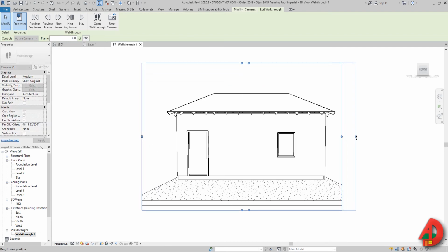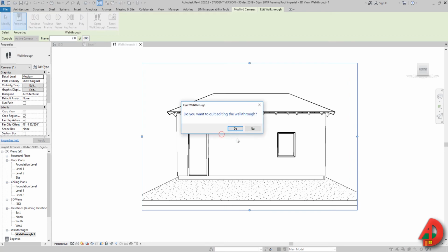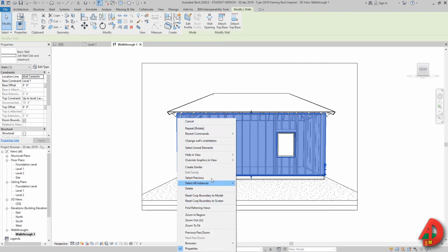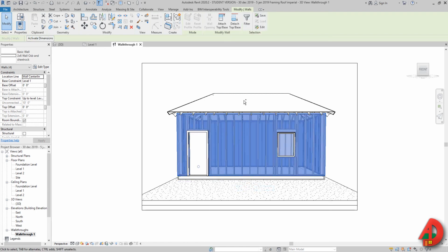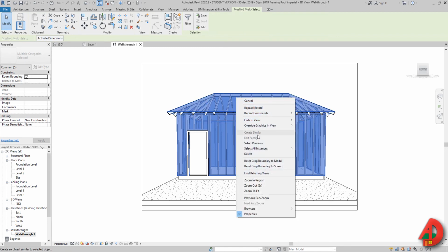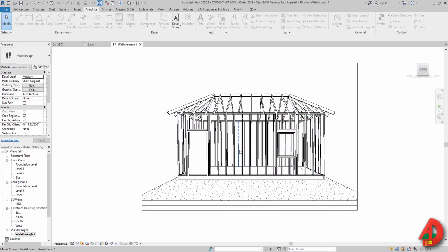What I'm going to do is select all the walls for this project, select all instances in entire project, and the rooftop, which is actually a plywood, and I'm going to right click the mouse and then hide in view elements. Let's say we want to make a presentation for some students on how a framed shed should look. After that, now I can set up consistent colors.